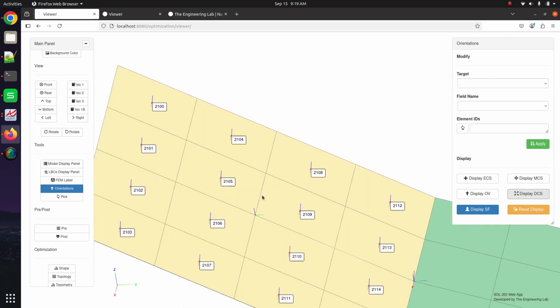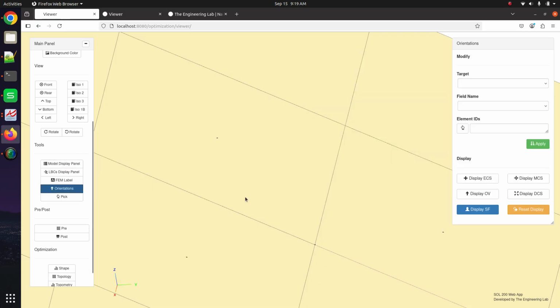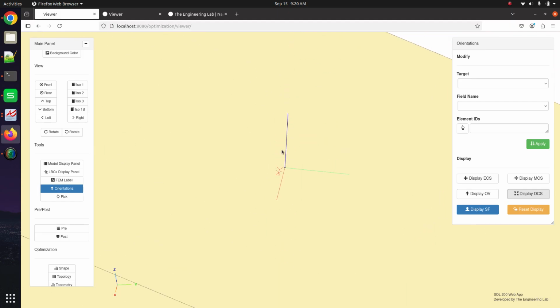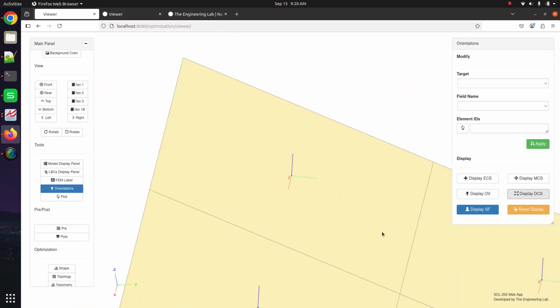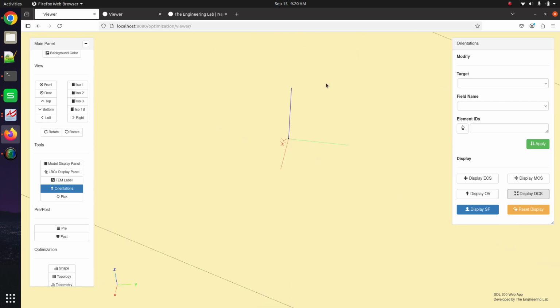Now, let's go ahead and turn off the labels actually. If you look very closely, now you have coordinate systems at each grid point. These are the degrees of freedom for your grid points, and we have stick figures just to communicate that your results are going to be observed by these individual observers. That's the whole idea in these degrees of freedom. There's an observer here that's observing deflections if this was a structure, but here these are aerodynamic grid points, so the values being observed are a little different. Okay, so we're pretty much at the end of the tutorial.